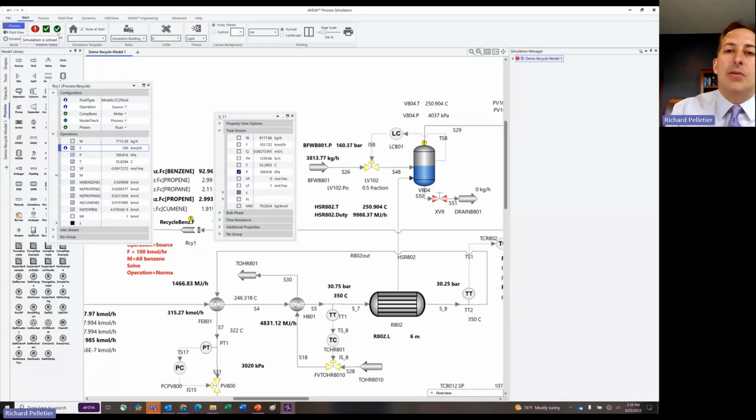And so that gap, that difference between the two values, is too large of a gap for the solver to be able to solve, right? And so I need to manually get this to close so that these two values are less different from one another. They're more similar to one another.